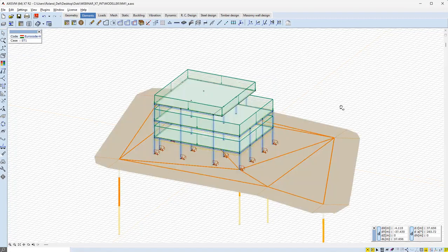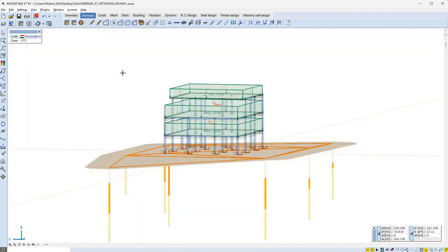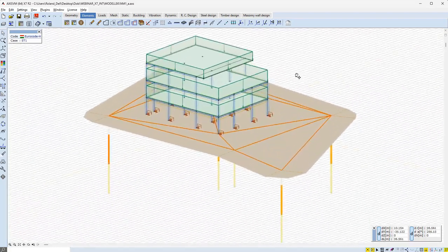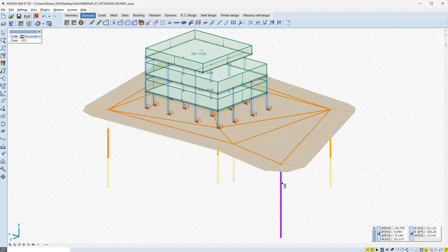Switching to any other view than wireframe view, the ground level of the terrain model will be visualized more heavily. Standing over a borehole with the cursor, an info window will show the layers, thicknesses, and the total depth. Graphical symbols of the boreholes and the terrain model can be turned on or off by choice from the bottom bar.